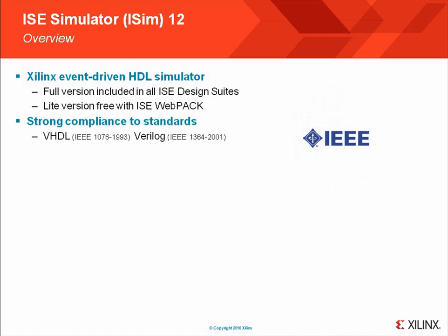ISim supports commonly used HDL standards like VHDL93 and Verilog 2001. It also supports mixed-mode simulations, allowing you to simulate designs that include both Verilog and VHDL code. It also leverages other standards, such as the Standard Delay Format, or SDF for short, used for back-annotating delays from a place and routed design in timing simulations. A Tcl interface for GUI and engine command scripting, and VCD or SAIF standards for using simulation activity data for power estimation.